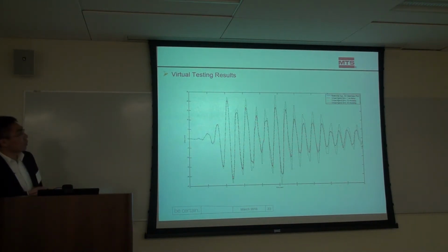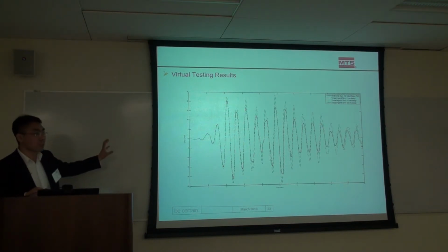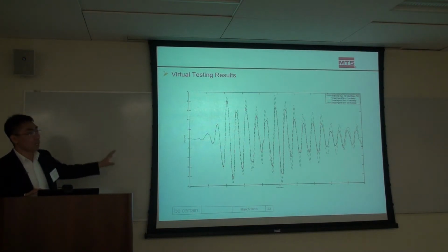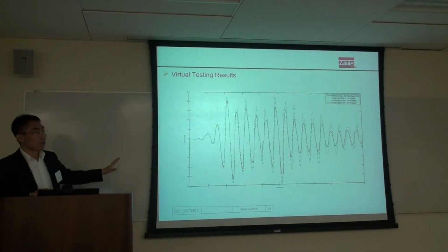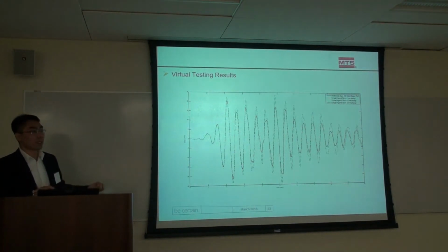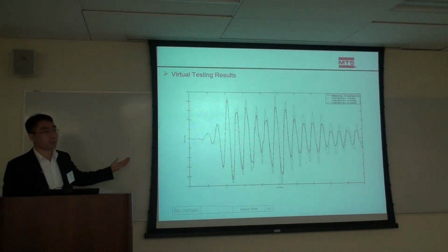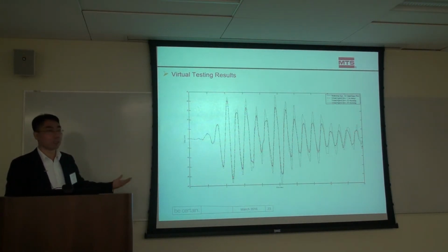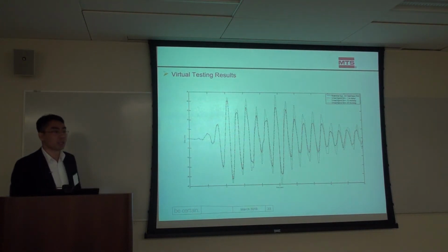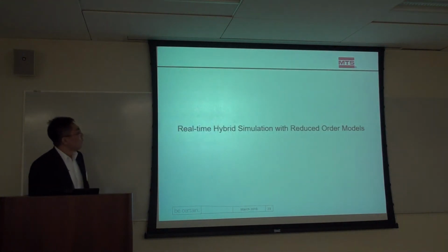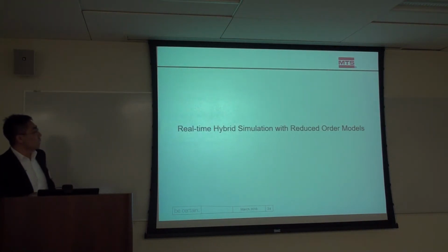This demo example 2 is just to give you an idea that, depending on this type of substructure partition, things become much easier to deal with. 35 milliseconds of delay is easy to achieve. You don't need any fancy outer loop controller compensator. The PID will do the work. You should be able to do that test. So that's about the system stability analysis.